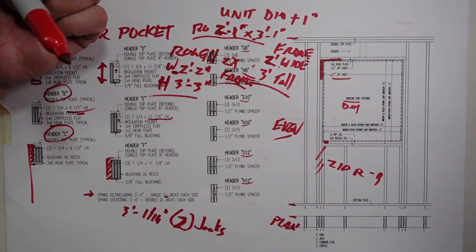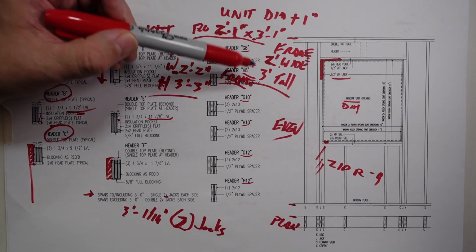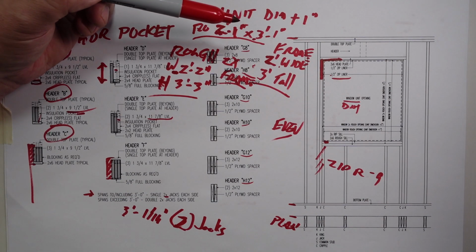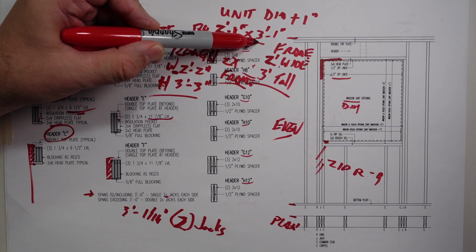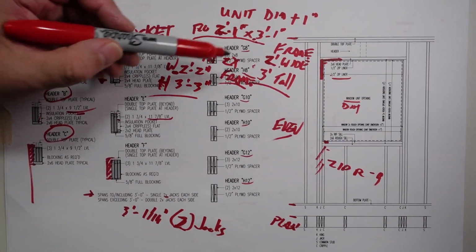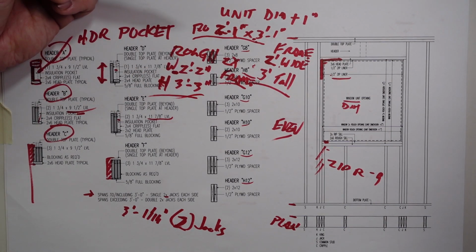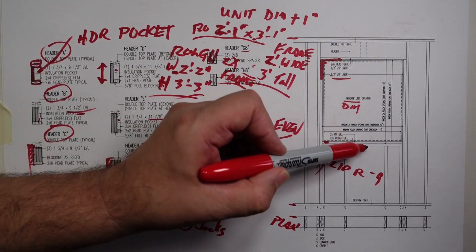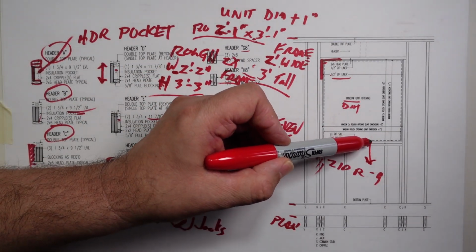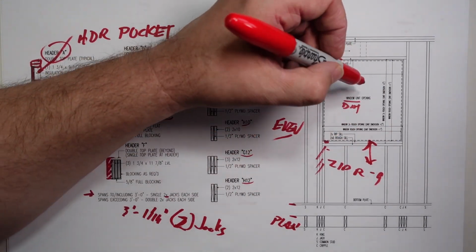We have our sill in there, our rip sill. So with our rip sill, we start out with a 3 foot tall window. We add the 1/2 inch rough opening, it goes to 3 foot 1, but then we add the zip liner and the rip sill, 2 inches, and that takes us to 3 foot 3 for the rough 2x framed opening there. So anyways, that is pretty much all of the planning that goes into it. And obviously the sill here is going to adjust in height to the window opening, whatever that unit dimension is, or what we say UD.